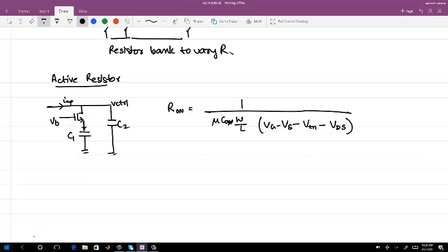The thing is, we all say this is a non-linear thing, but we know that this PLL is going to oscillate at a given frequency, and we know this is going to be this control voltage. In a steady state, ideally the current which is going into the loop filter is on average 0. That's more problematic than the non-linearity, though non-linearity exists for sure.